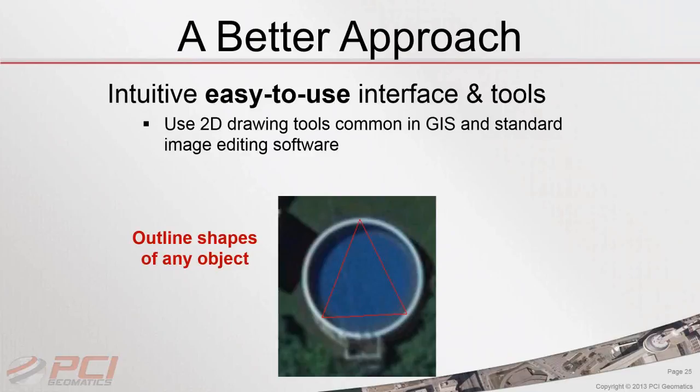There are a lot of drawing tools that make it easy to pre-configure different features. Here we see a swimming pool that has a circular shape, so rather than having to draw all vertices along the edge of that, we could just draw 3 vertices and then it calculates the exact perimeter of that feature. There are other types of complex roof types that can be pre-generated.